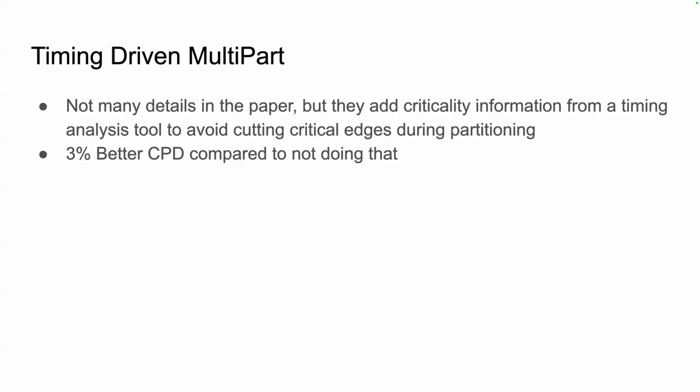You don't update with anything that happens to the rest of the netlist, but if you just did one timing analysis and said, find the longest path to every single input cut and mark that with a set input delay, it is accurate if none of those outside delays change.